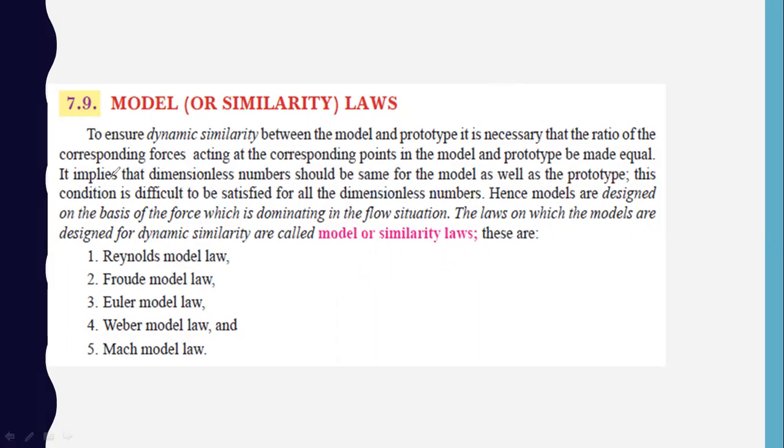It implies that dimensionless numbers should be the same for the model as well as the prototype. This condition is difficult to be satisfied for all dimensionless numbers. Hence, models are designed on the basis of the force which is dominating the flow situation. The laws on which the models are designed for dynamic similarity are called model or similarity laws. So this is the definition. We will see them one by one.